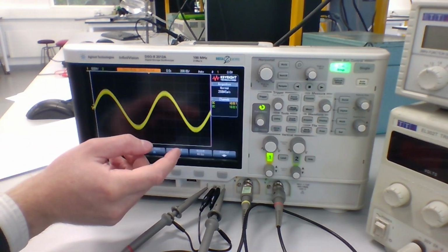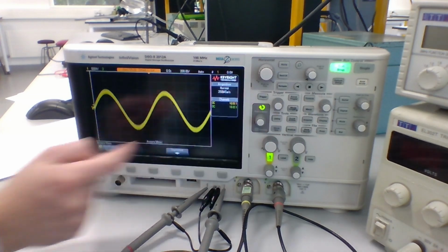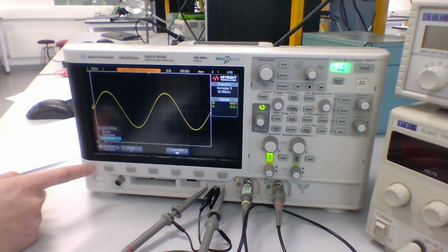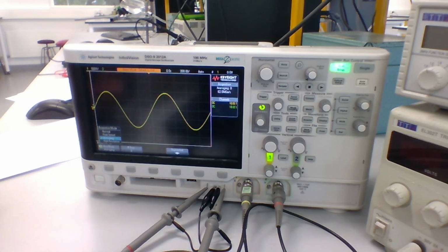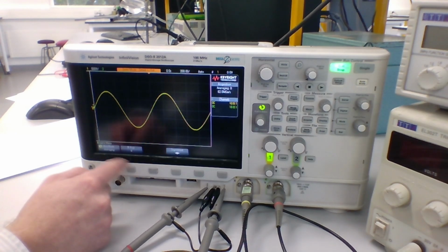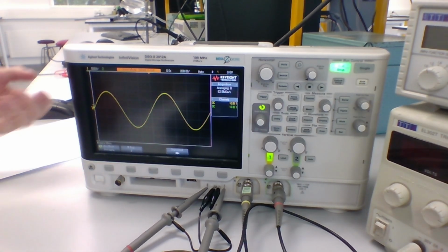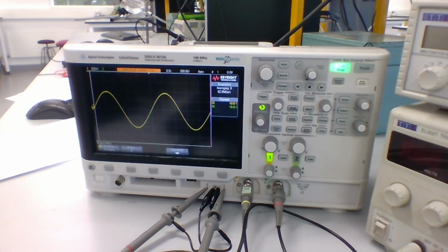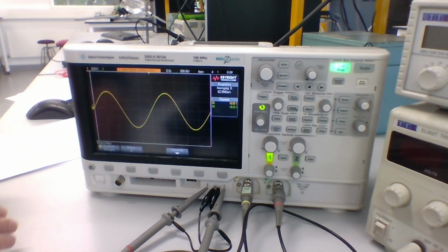If we press the acquire button on the front panel here, we can change the acquisition mode from normal to what's called averaging. What this does is effectively use a pretty simple moving average filter to average the signal on the screen. By default, it will take 8 samples to average it. We can change that if we want to. And so this can be a nice way, again, of removing noise from a signal. Bear in mind that averaging a signal has its own effects on the signal itself. If it's a periodic signal like a sine wave, we're generally okay, but if it's something aperiodic, we may run into problems. So just be aware of what effects that has.